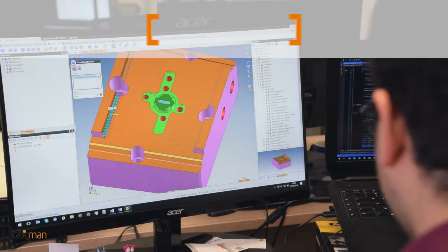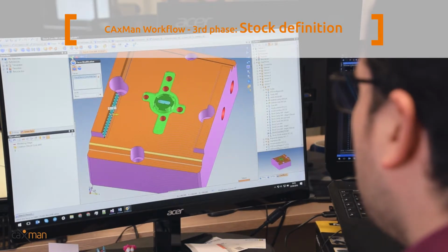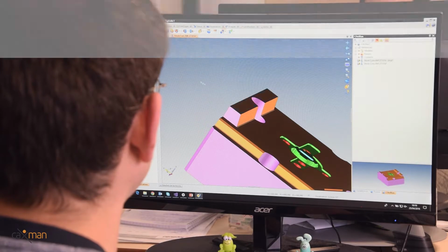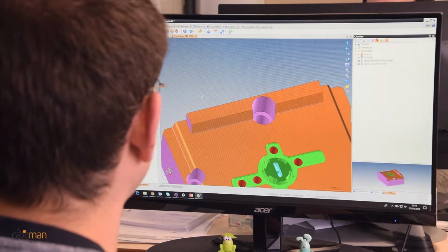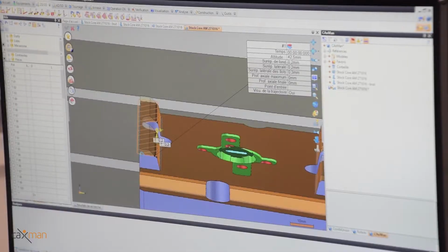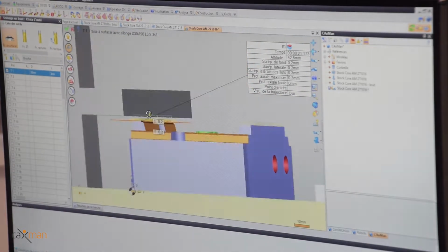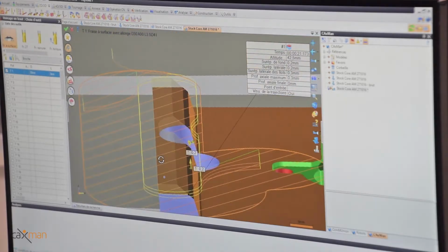For the mold to work efficiently, it needs to have surfaces with very good roughness. The most important surfaces are the parting surfaces, where the core and the cavity join together when the mold closes, and the surfaces defining the part to produce. It is also important to have good surfaces for the ejection system.